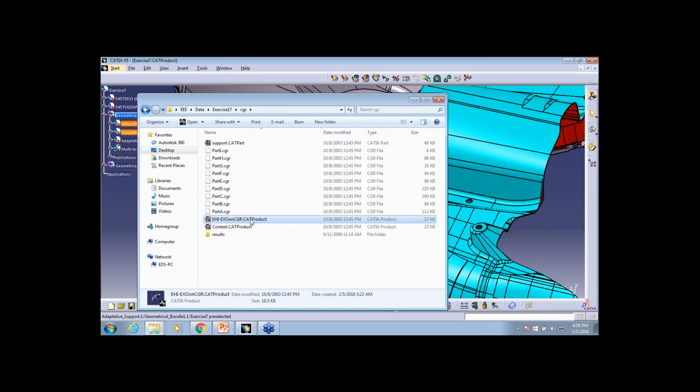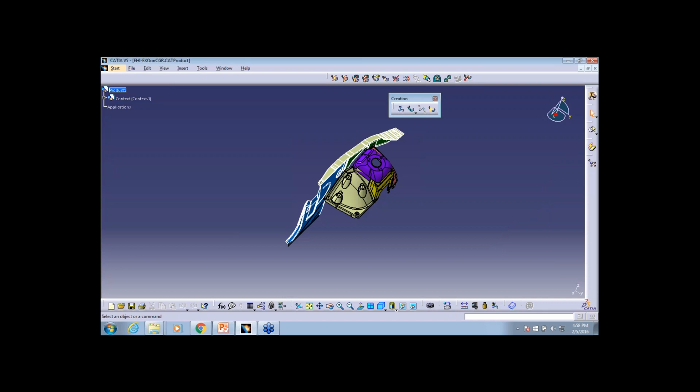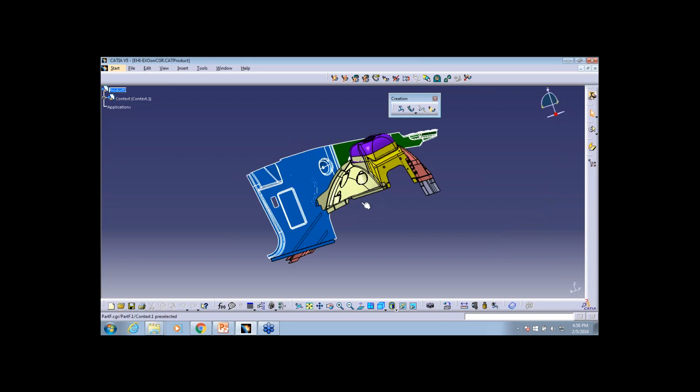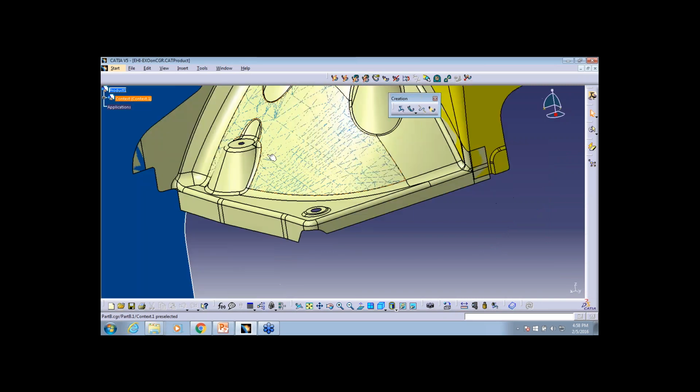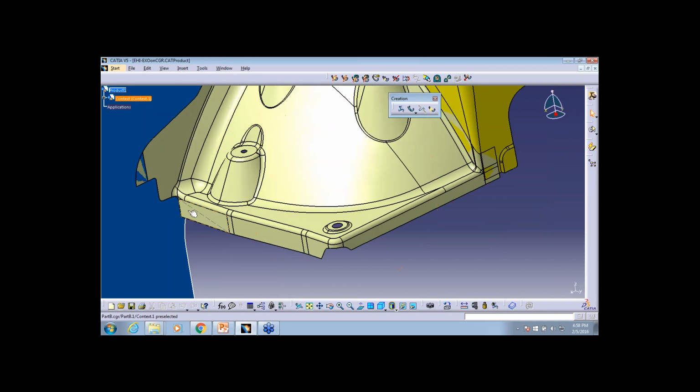Yeah. So CATIA EFA electrical harness has the capability to have lightweight data also. So here what we are going to do, one way of routing is using the clamps. The other way of routing is using the surfaces, where I'm going to use this surface as a reference.